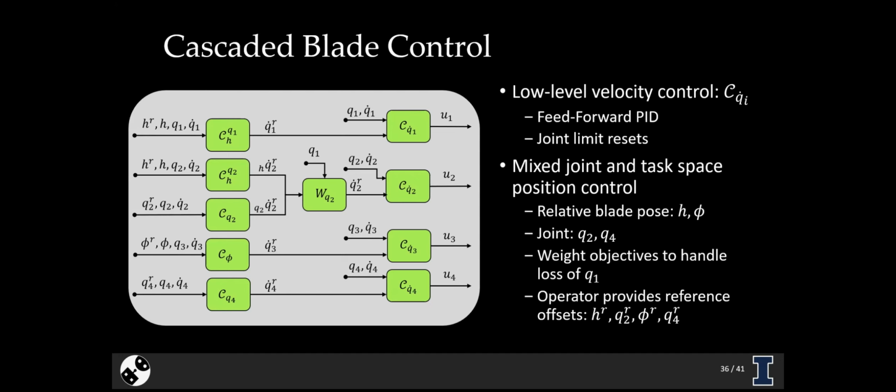So when the vehicle hits its lower limit on that Q1 joint, which happens a lot during the bulldozing operations, you want to be able to still have control over the height, and we can use the pitch axis for that in that scenario. But when we're off that joint, we'd like to have our pitch set so that we're achieving a good blade angle with respect to the terrain. And so this method to mix these two objectives for the Q2 axis was developed.